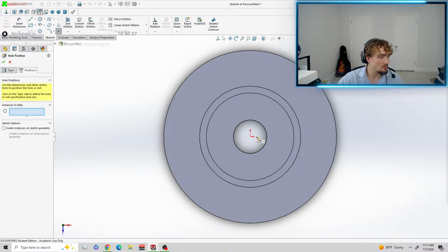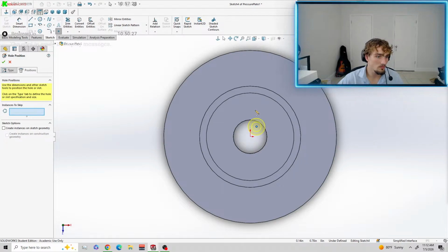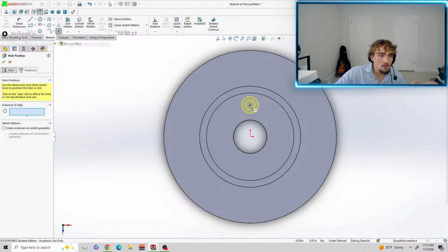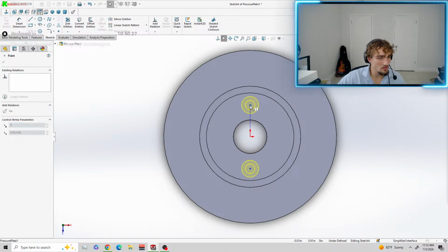Why am I no longer doing this? Now I did it. Click above it. That's what it means. Click above the center hole. Okay, so right here. Move the pointer under the center hole so the inference center line appears, then click to place another hole. Okay, now I'm understanding. Press Escape to stop. Drag the first hole onto the inference center line. Yeah, like this.